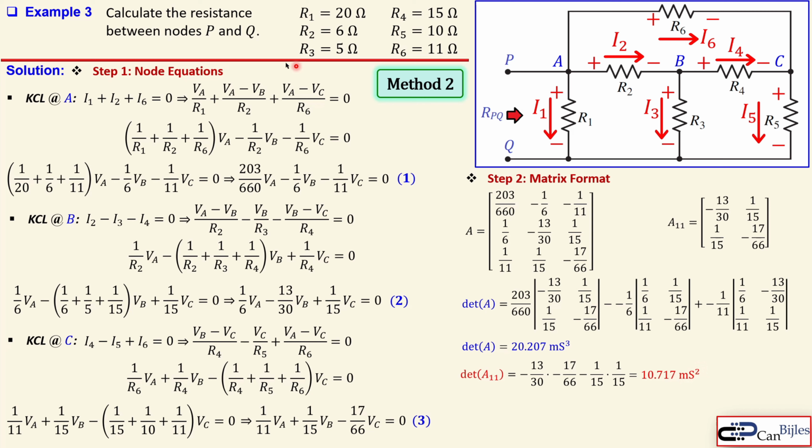Now in order to get the resistance, which is then in ohms, we need to do determinant of A11 divided by the determinant of A. Because if you do the determinant of A divided by the determinant of A11, you will get still the unit as conductance. We then need to invert that. So we'll do that right away. That means there will be then this.